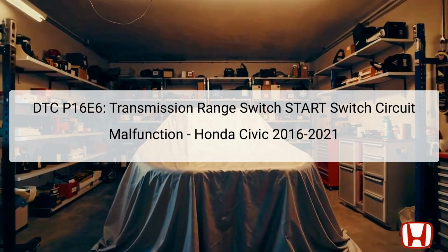The PCM uses this information to manage engine performance and control startup operations, ensuring that the vehicle can only start in a safe gear position, such as park or neutral. A malfunction here can lead not only to starting issues, but potentially compromise overall vehicle safety. This guide will outline how to troubleshoot and resolve the P16E6 error code systematically.